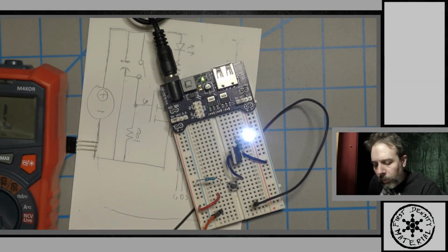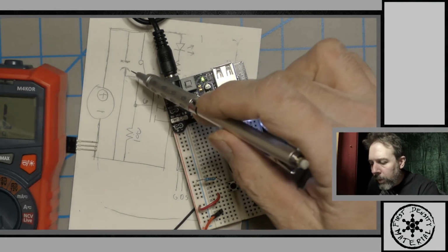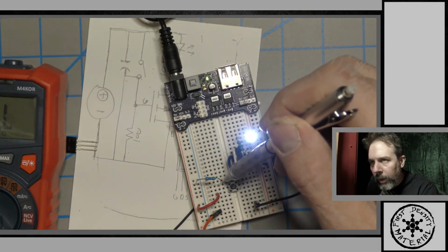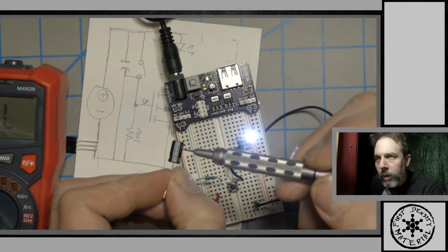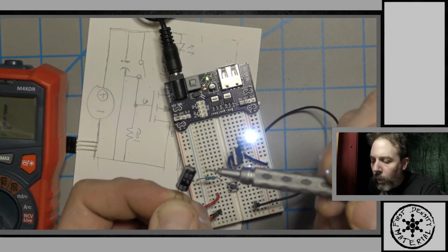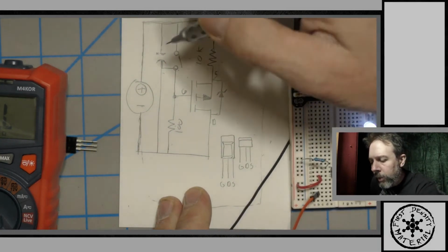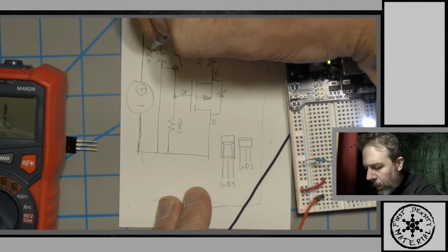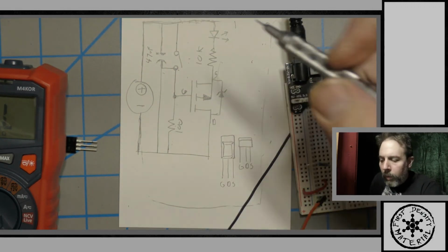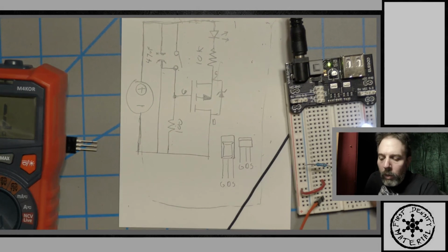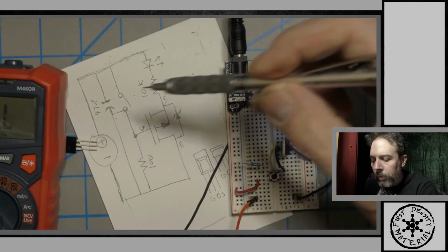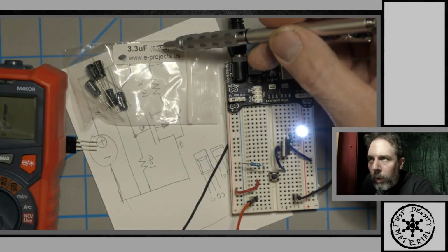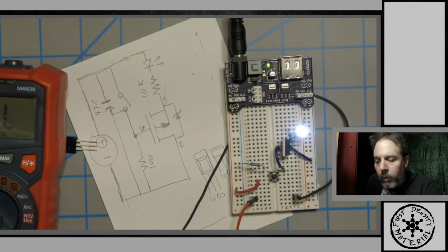So what we want to do is have it slow bleed on. In this case, we have to hook the capacitor up between the positive, this, and the negative, this. If you look at the capacitor, it has a negative stripe on it. This is a 47 uF capacitor. You can use any capacitor for it though, and the lower the number, the faster it makes it. So if I used like a 3.3 uF, it would be certainly a lot faster. You wouldn't notice a slow burn.